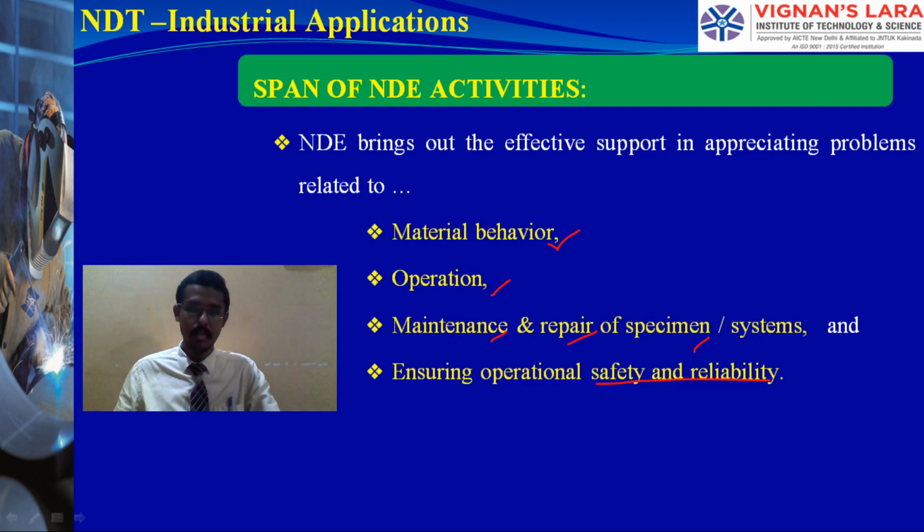So that we can find the material's behavior and what operations cause the discontinuity. In welding, for example, TIG welding or SMAW. During high temperature in TIG, there is a chance of the tungsten electrode breaking and tungsten falling into the weld. That depends upon the operation parameters, current and voltage, high current. Those things and all operation management systems.